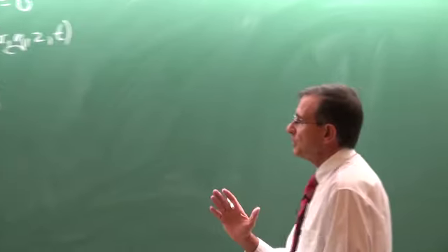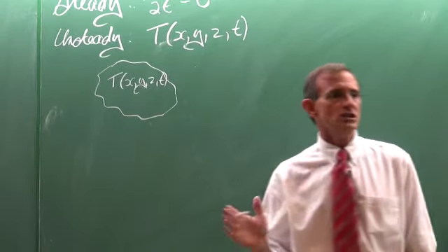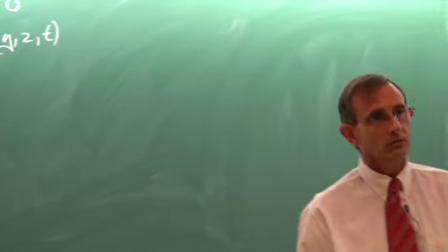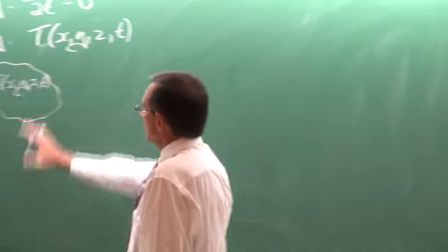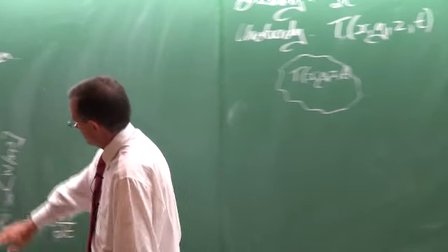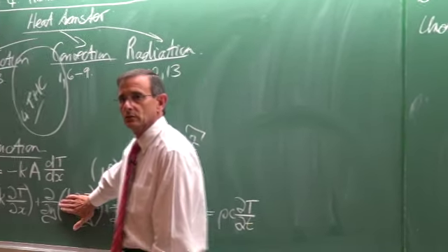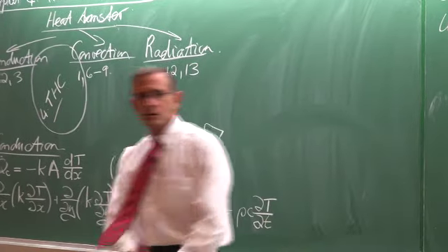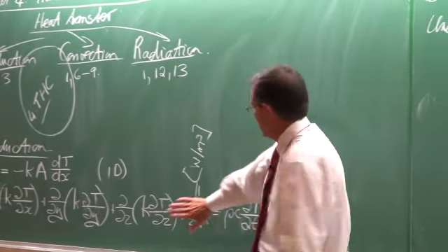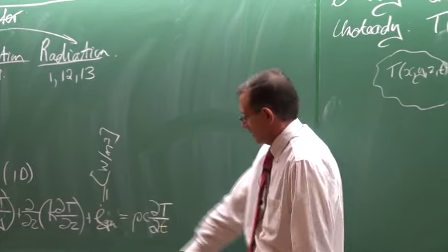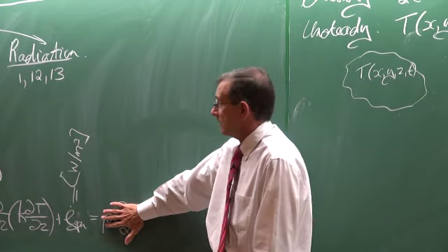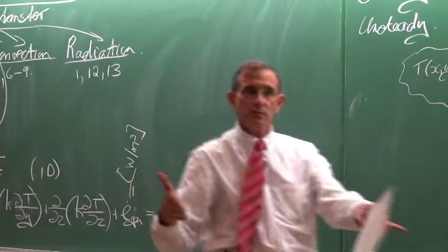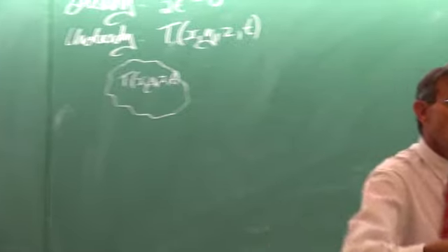The third approach that can be used, and that is a good engineering approach, is to say, well, let's start simple. We try to make things as simple as we can. So we do not say it is a three-dimensional body, so we throw away that term and that term. We say that k, the thermal conductivity, is a constant, nothing is being generated on the inside, and we throw away that term, and then we've got that equation, and then we can start solving practical problems. And then slowly we can start making it more complicated.